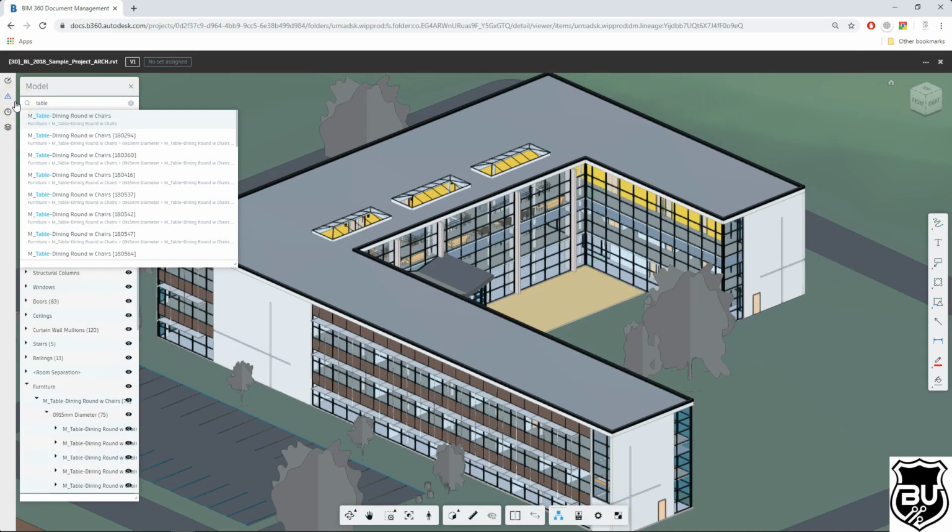So this model browser feature is very useful for finding the quantity of objects, or if you want to find the location or the context in which the elements appear in the entire project. This is the feature that you can go to. One thing to note here is you might need to have prior knowledge, and I believe not everybody in the team will be a modeler.